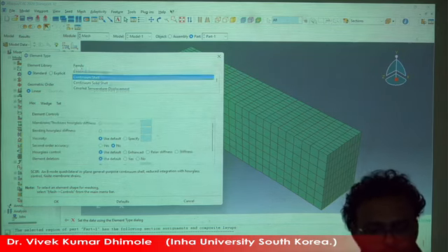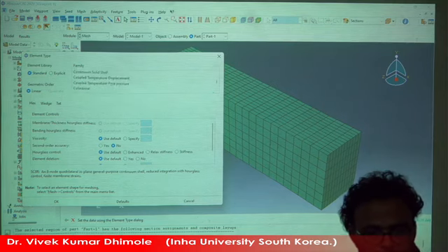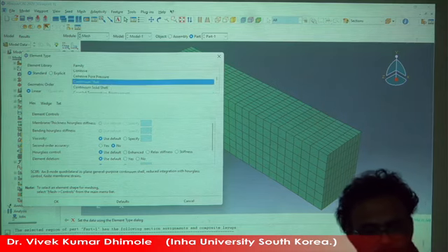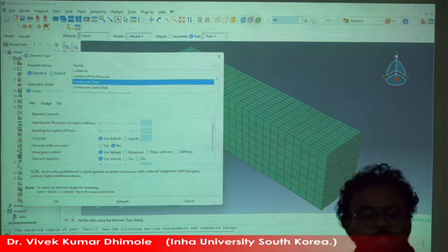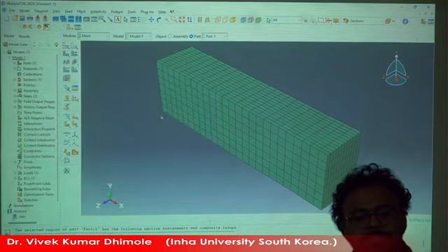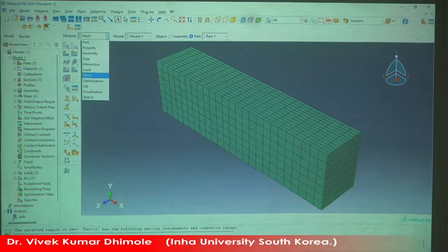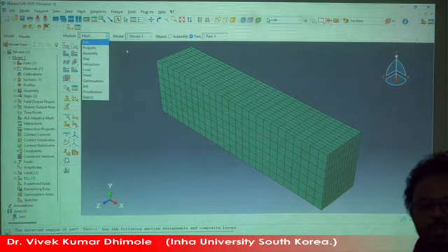So we are just using the continuum shell element. You can choose solid as well, and you can choose explicit element when you have explicit analysis, but we are doing static general analysis, so we don't need the explicit one, and we say okay. The element is decided, everything is decided. If there is a chance we missed something, when we run, it will show you the points, do this, do that, right? It will show you, then you can do it, right?